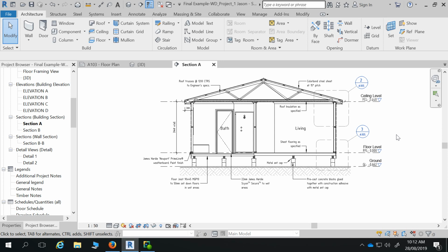Yeah, so I just do a copy of that roof and do a paste in the same place, but then give it an offset. And then I go in and duplicate that roof. So I do an edit properties or go into type properties, duplicate it and change that one to 16 mil. So then it just sits above perfectly, so I don't have to worry. And then all I've got to do is edit the sketch and extend the outer sketch lines just far enough so it sits over the gutter. All right. So it's a pretty quick way to do it.